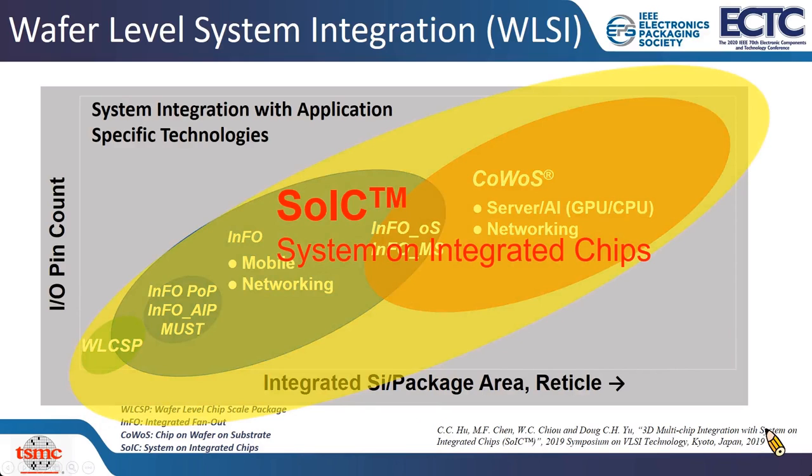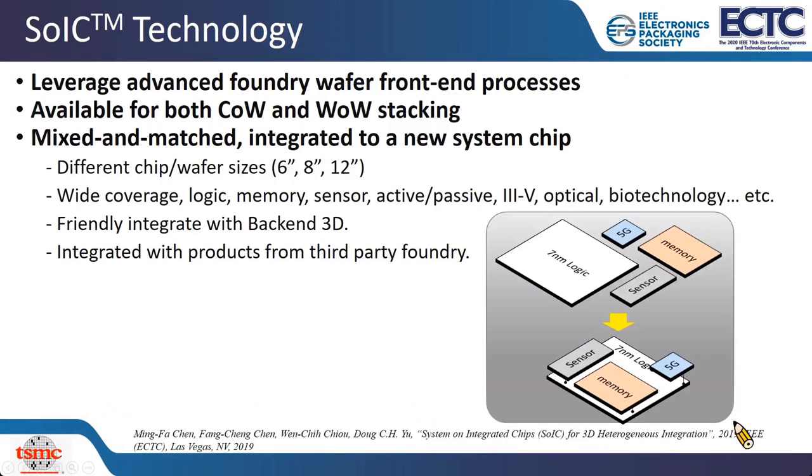To solve the problems, we developed SOIC technology to perform wider coverage of wafer-level system integration without solder bump, with ultra-thin bonding interface and high pin density. So, what is SOIC? It is so-called System on Integrated Chip. Our team first reported SOIC technology in the ECTC conference last year, 2019.